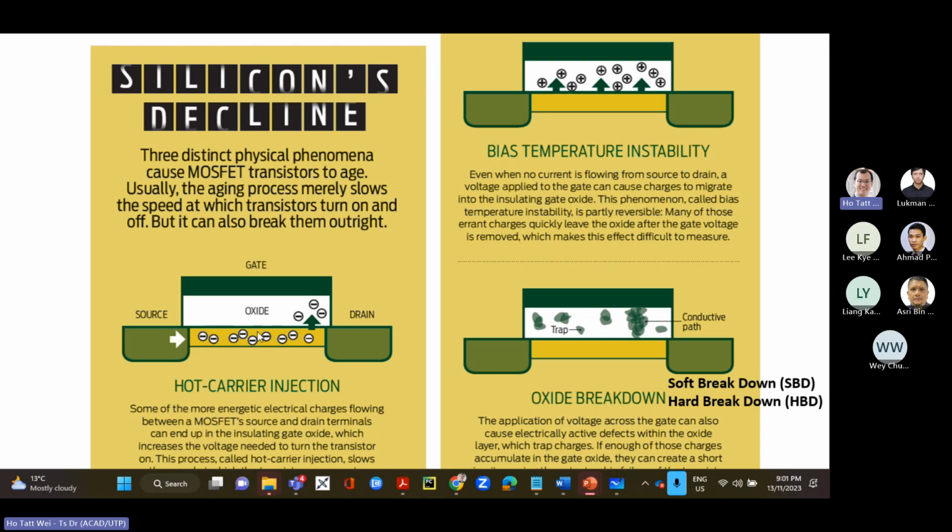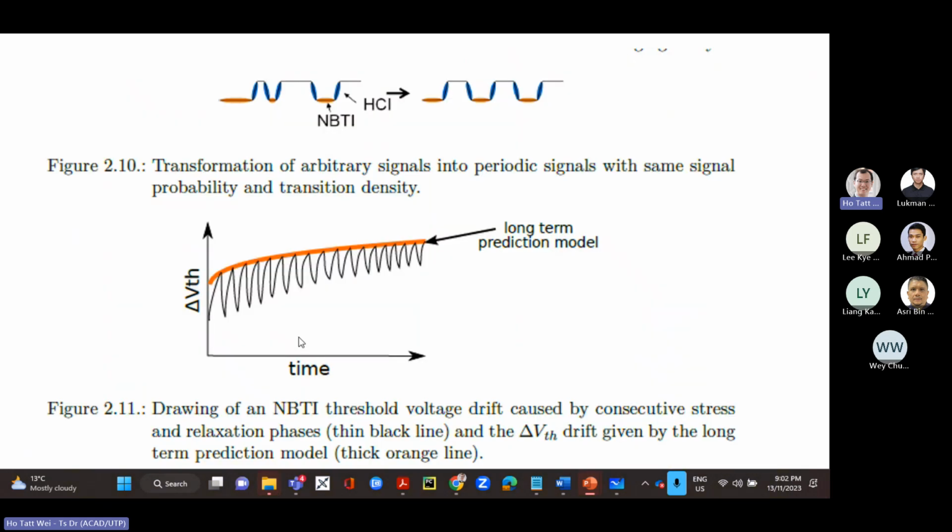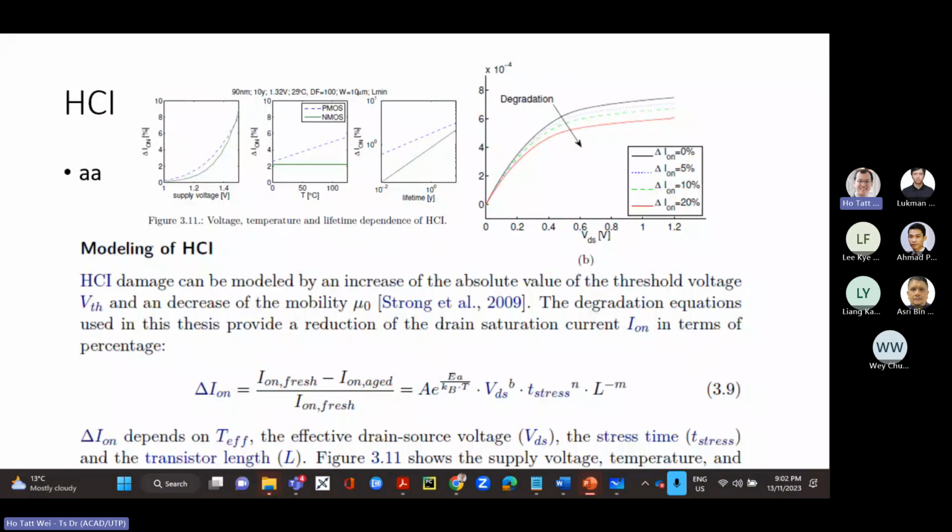So you look at a change in threshold voltage. But also when you're actually moving here, you suddenly will have additional charge here that is kind of deflecting, disturbing the motion of the electrons or the holes here, right? So these additional charges in the oxide not just are reducing the number of free carriers here, they're also interfering with the flow here, because it's as if you've got a bit more attractive forces that will kind of distract the charges from flowing here. So they get effectively a little bit slowed down. So there are two ways where HCI is actually changing things. It's changing mu and changing VTH.